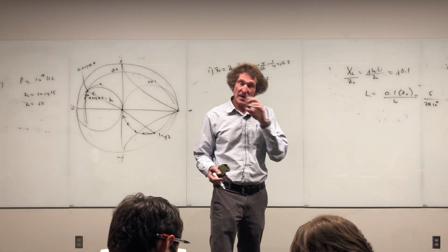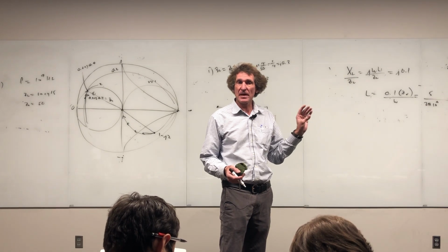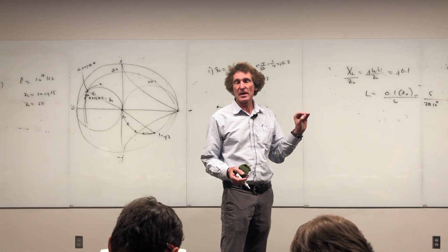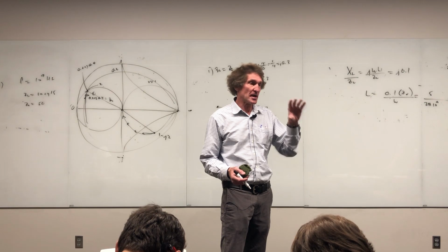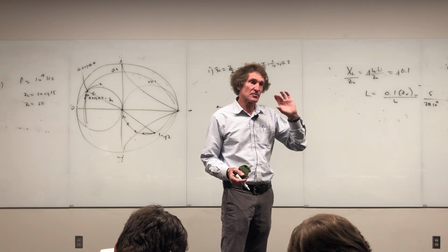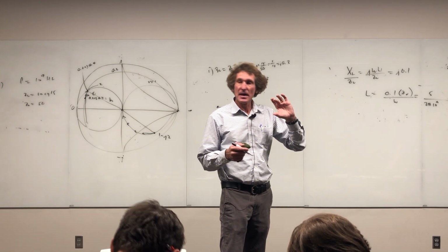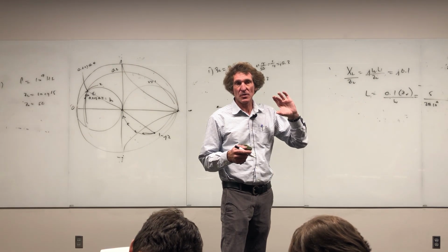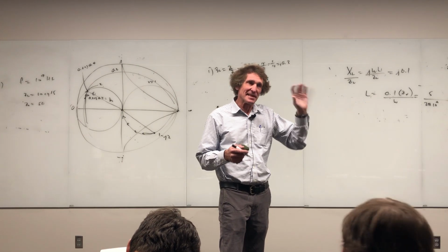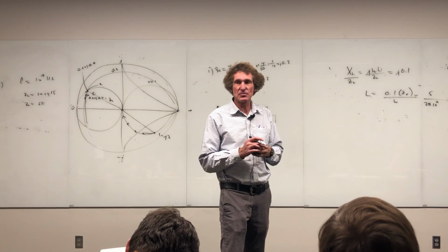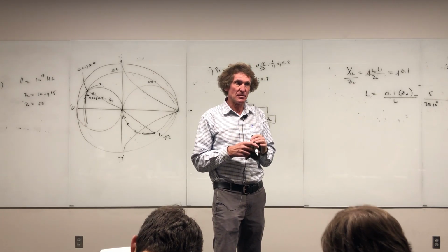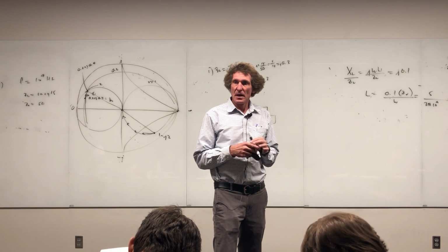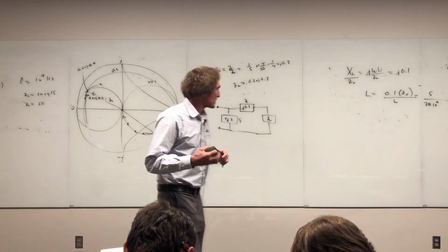And the other thing is when you're feeding an FET, it's not that big of a deal. A true field effect transistor has just about zero DC current, where you've got an oxide beneath the actual gate. It's a metallized gate. It's just like a capacitor. So it doesn't draw DC. It does a little. There's this super small trickle current, but it's not appreciable. It's not supposed to be there either, but it is.